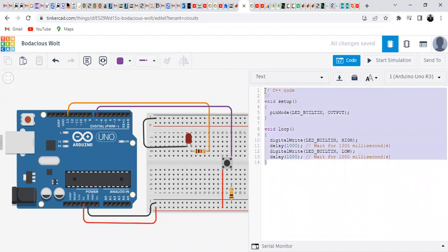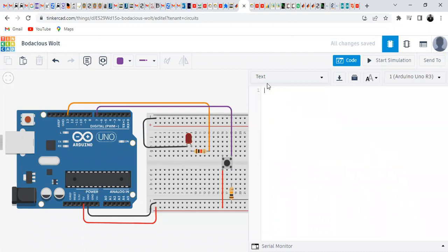Here you're coding using C++ language or Arduino language. So I can write my program here quickly. I can put the first variable, integer variable LED, and assign it digital pin number 13. So in this case, we are connecting the LED to pin number 13.